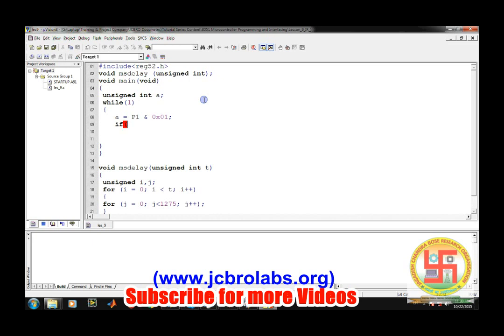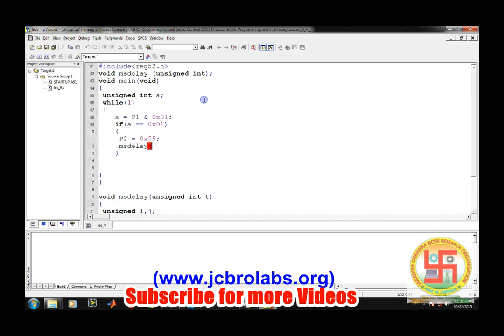If there is an obstacle in front of the sensor, a content will be 1. So if a is equal to 0x01, port 2 output should be P2 equals 0x55, and then we should call msdelay 100, and then P2 equals 0xAA, and then msdelay 100, and after that it will again check the status of the pin. So here we are checking the status of the sensor.